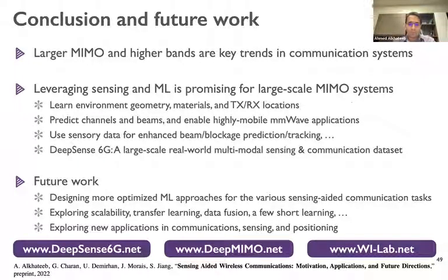So it's still very useful. Maybe you get one order of magnitude less dimensionality, or a less complex problem, and then use over-the-air training to have a robust result. In my opinion, this is a practical, robust way to do channel and CSI acquisition using machine learning. You can also use visual data to predict the channel covariance. We have a paper on this. Then you can use the channel covariance, maybe the dominant subspace of the channel in massive MIMO, to refine and estimate the channel.